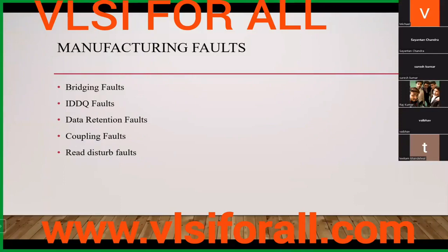When you want to read something from memory, and during that read process some other cell gets disturbed, that value may change. The neighboring cell's values change when you read that particular cell. That fault we call a read disturb fault.